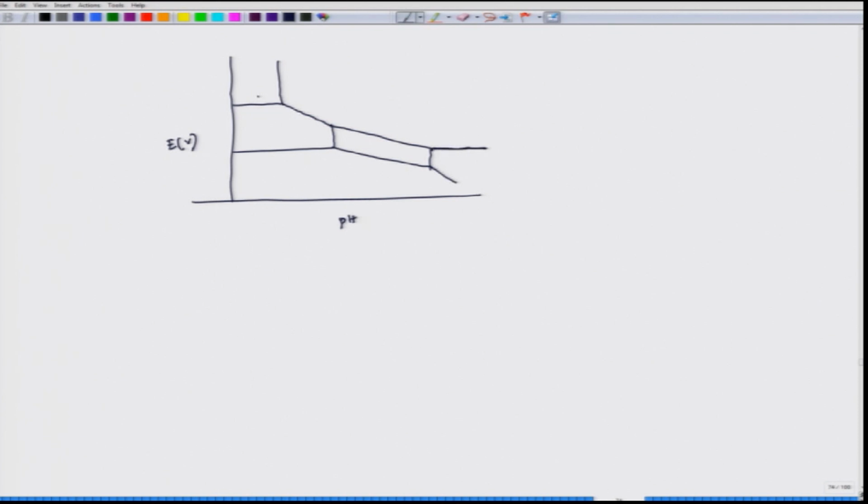So, this is the diagram what it looks like, where this is Fe, Fe plus 2, this is Fe plus 3, Fe(OH)2, and this is Fe(OH)3, and this is HFeO2 minus. Now, here also this phase and this phase, they are insoluble phases with a very low solubility product. When they form, they try to form on iron surface and they try to passivate.